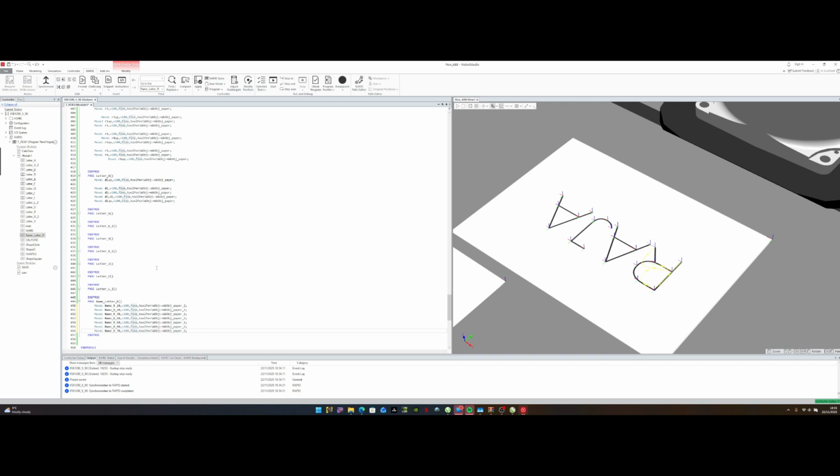Okay, so we've done it this way now. Next, we need to understand what we're trying to do here. I'm just going to save this because I will sync it back to the station very soon. We're trying to move from this target to this target linear. Okay, that's the first move. Move L. Then from this target to this target linear. So that means move L, R10, because this is R10.